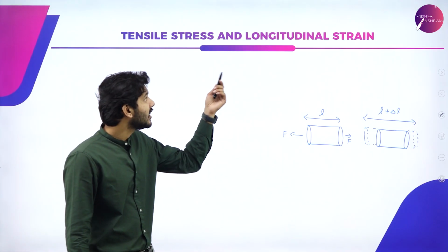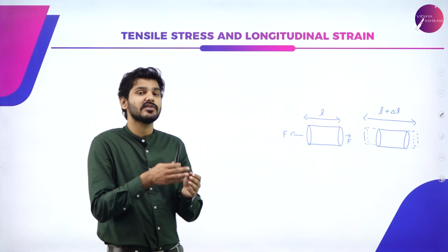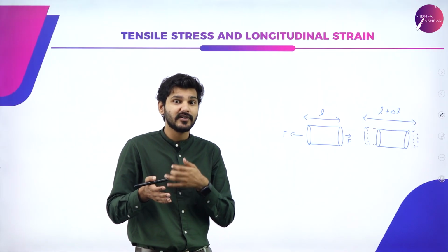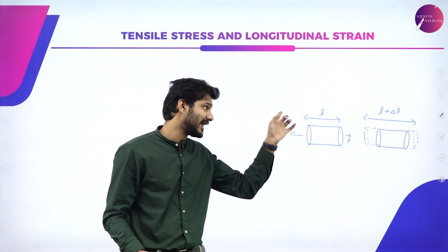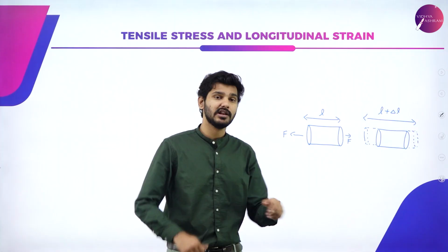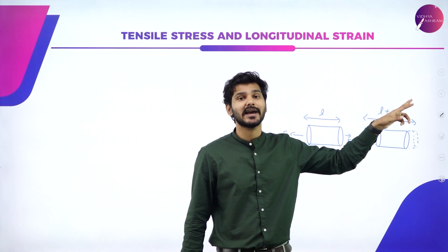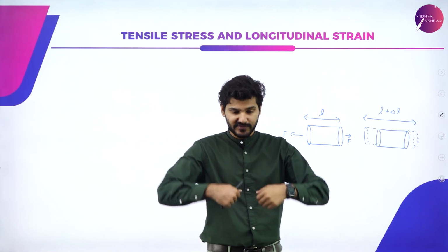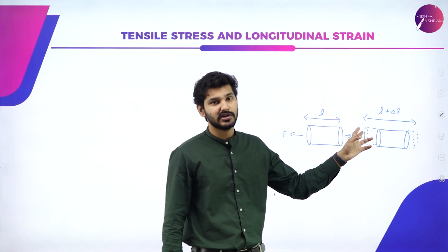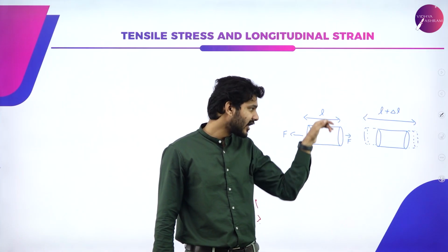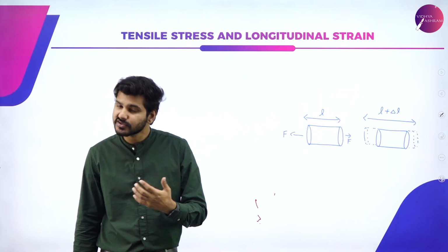And what is longitudinal strain? Strain is the ratio of change in dimension to the original dimension. Here the changing dimension is length. So initially if it had a length of L, through my pulling or pushing, you have a new length, delta L, that is being added to the original length, because we are stretching it out, right? So the change in dimension, delta L, divided by the original dimension, L, will give you longitudinal strain.